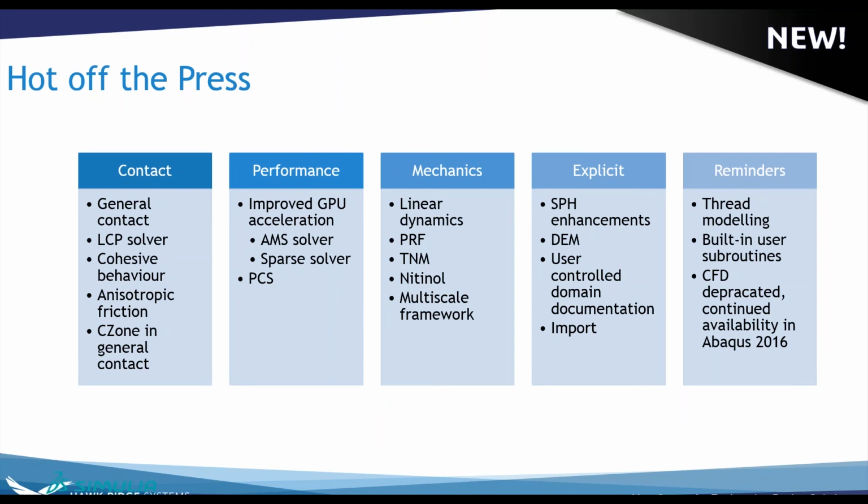Research has gone into the composite damage models for Abaqus Explicit and a few other key functions, like the Abaqus plugin for welding and additive manufacturing. Another key one, which is a usability enhancement, allows you to control displacements through space and time. So rather than controlling a displacement with a load increment, you can describe a three-dimensional path through time. So that's a key one.